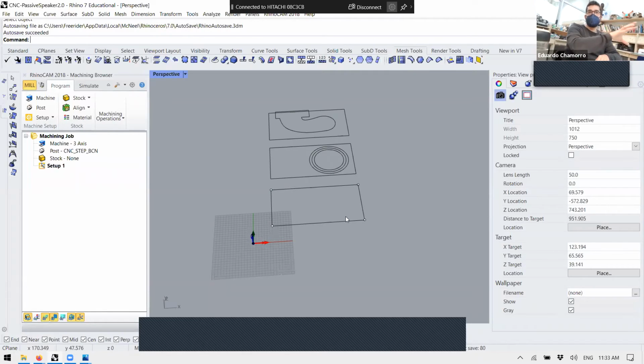No, we launch one file, finish, we change the end mill, we set the Z again, and then we launch the next file. It's the same process as the SRMs. We can enable these features, yes, but more automatization means more prone to mistakes if you forget one step.